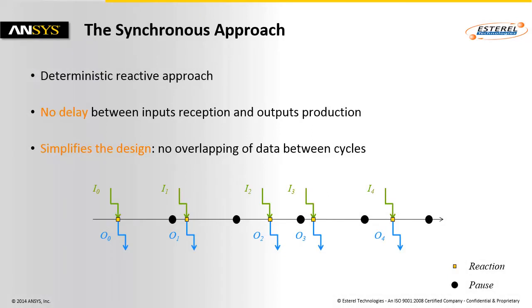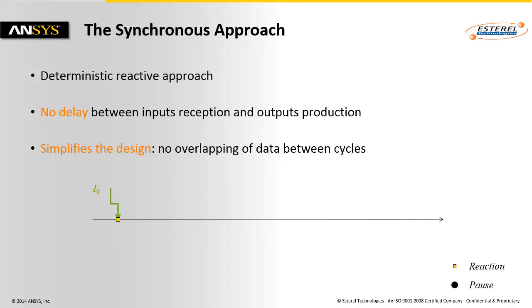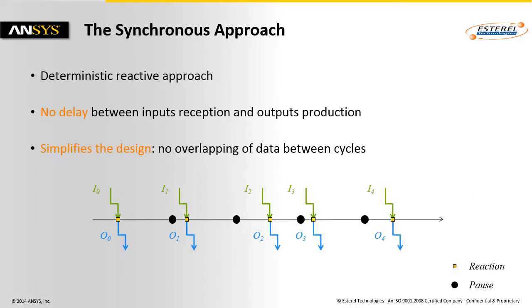The synchronous approach is a deterministic reactive approach. As I already said, the outputs are only determined by the inputs and their occurrences, and the synchronous approach is deterministic. This states that there is no delay between inputs reception and outputs production, and this greatly simplifies the design of the application. There cannot be overlapping of data between cycles.